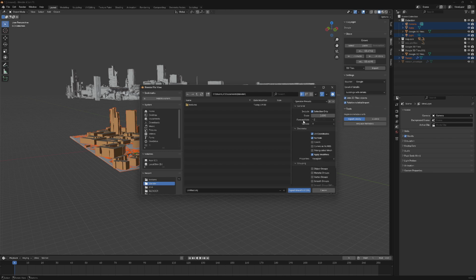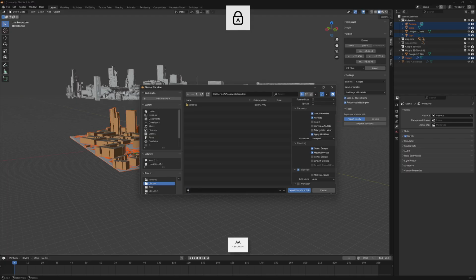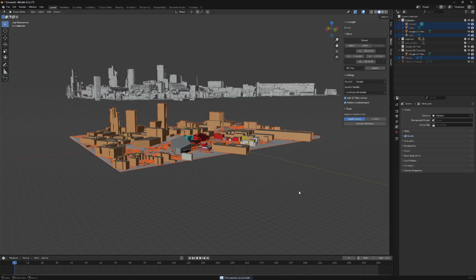So I'm just going to make sure that I select the different file types that I want. And another thing is that by default, Blender exports things out with Z forwards. And this is because in the film industry and the game industry, cameras typically use Z as the depth of the camera, as opposed to the height of the camera, or where the camera is in terms of its height. It'll mainly work on how far the camera zooms in and out. And so we need to make sure that Z is actually pointing upwards. So we can do that here. We can change that here to Z pointing upwards, which is fine. And then we can do material groups, and we can do objects as groups, and give this a name. So Manchester MSA, for example,